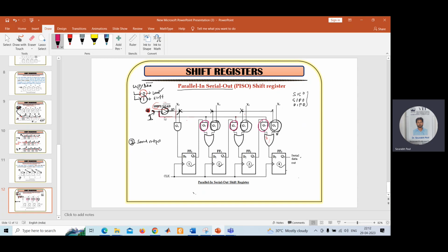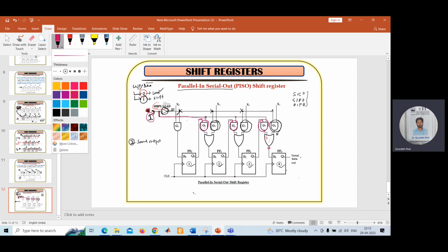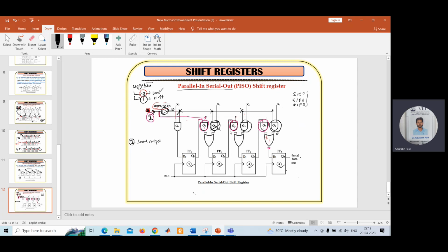How am I saying this? Because see, this is connected to 1. So one of the terminals of G5, G6 and G7 is connected to 1. So whatever input is there in the other terminal of these gates, that will be the output of this OR gate. Understood? Because when we are applying 1, these gates are deactivated, this becomes 0, meaning G2 is deactivated, G3 is 0, G4 output is 0.